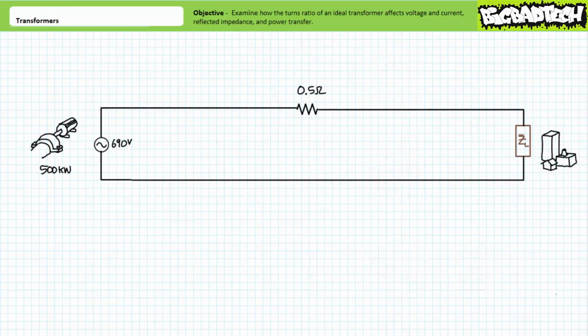In a larger sense, transformers are absolutely essential to getting power from where it's generated to where it's being used. Step-up transformers make it possible to transmit massive amounts of power over long distances with extremely small losses. Allow me to demonstrate. For this example, let's assume voltage and current are perfectly in phase with one another, and as such, all of apparent power will be directed towards real power and none of it towards a reactive interchange.